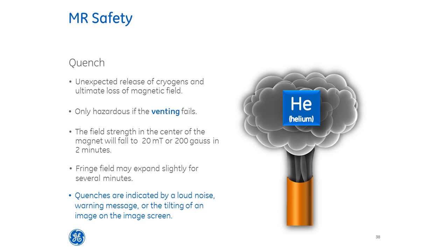As stated before, under normal operating conditions, even in the event of a quench, the cryogens pose no real threat to safety. However, as the liquid helium turns to gas, it needs to go somewhere as it expands. There is still no threat to safety, as there is supposed to be a vent stack that will release the gaseous helium out into the atmosphere. However, if there is some reason that the vent stack fails, there could pose a risk for the patient and the personnel. The point that is important to make here is that the customer is responsible for the vent stack.